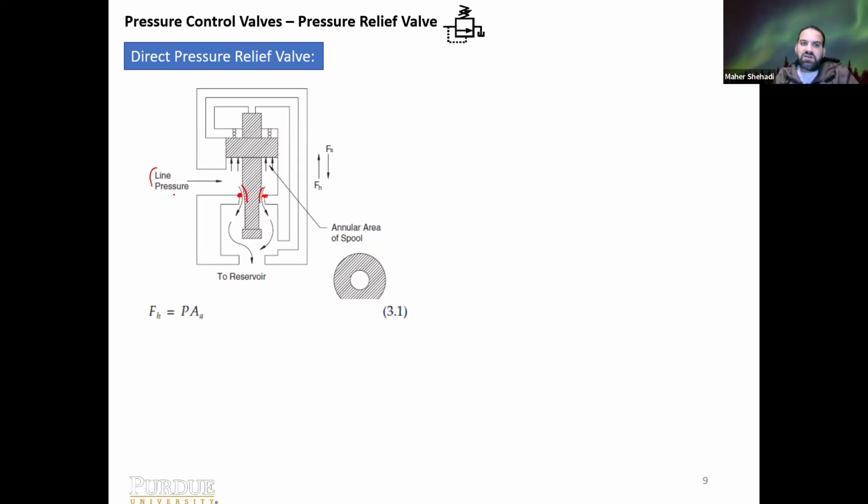So that's the line pressure, the pressure before, or upstream of, the valve. And that's the spring right here. We set the spring at a specific force, which gives us enough pressure to keep the piston down. Now, the pressure inside that line is building up. What would happen? There is more and more pressure pushing, since this is blocked and nothing can go through.